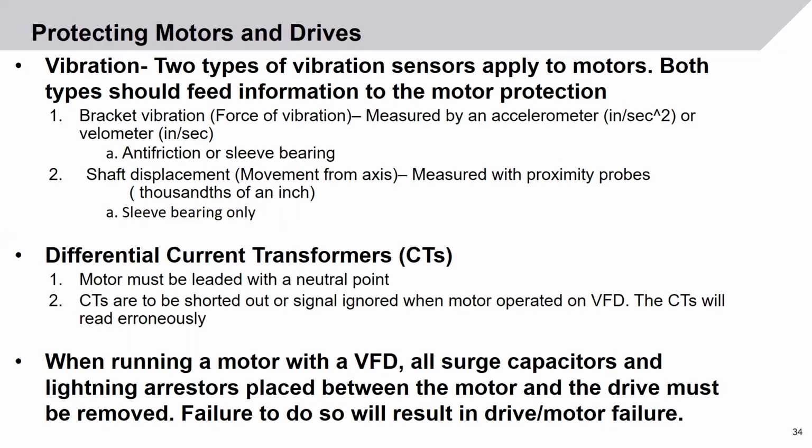But when you're running a motor on a VFD, any surge capacitors and lightning arresters placed between the motor and the drive must be removed. If they are not taken out of circuit, it will cause catastrophic motor or drive failure.